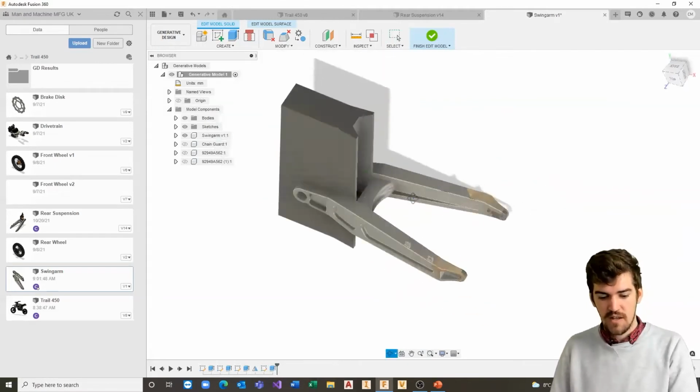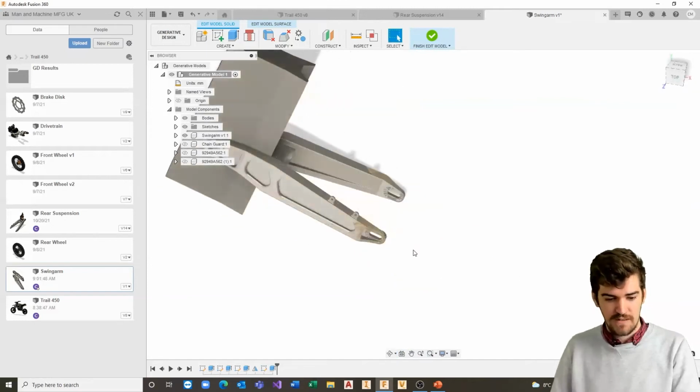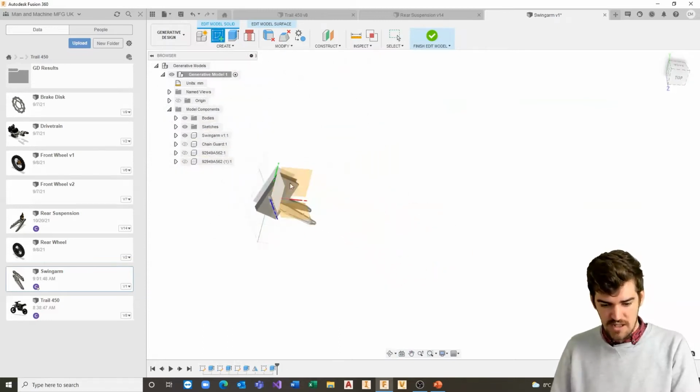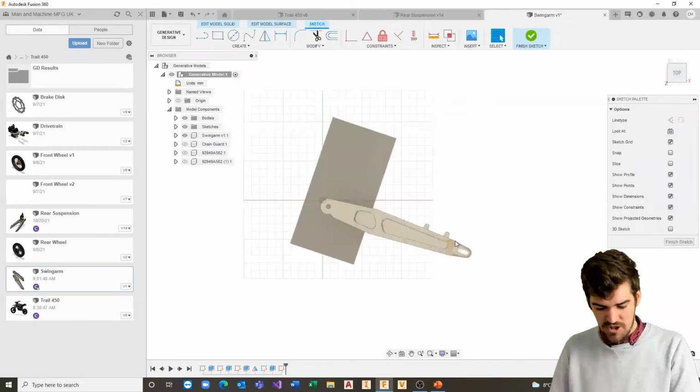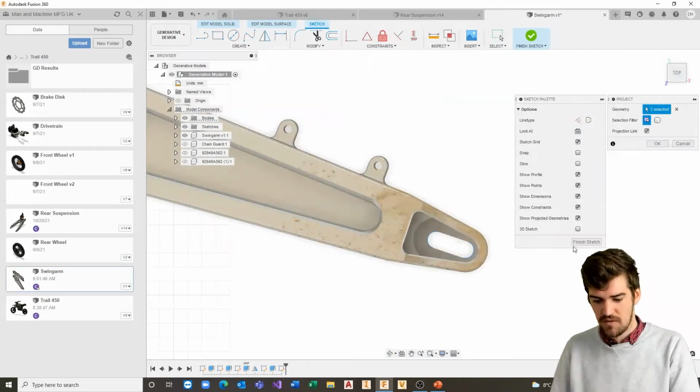and then we'll add a bit more obstructive geometry in a sec. The next thing we want to do, obviously, is create a wheel, or a representative of the wheel itself, and we're going to create that on the XY sketch plane. I'm going to project the existing geometry again, just to find the two centers of the wheel, to make space for both sides, depending on how you place your wheel there.